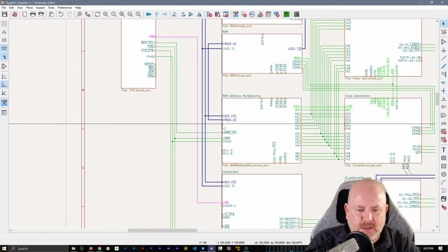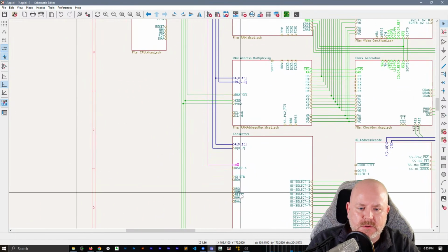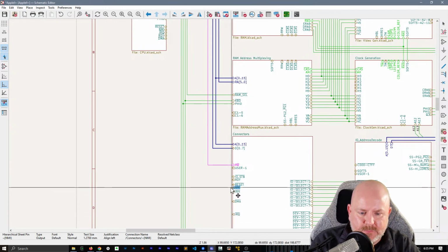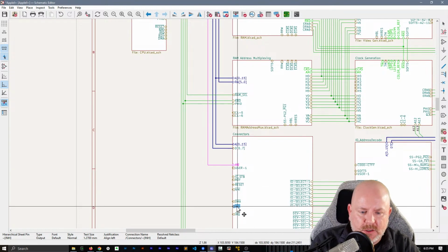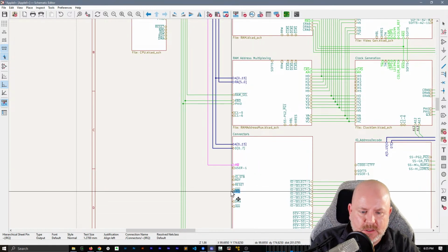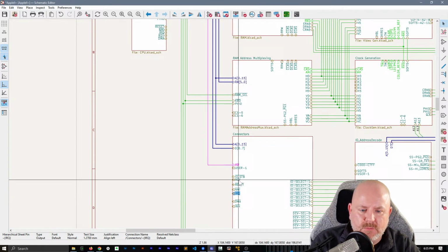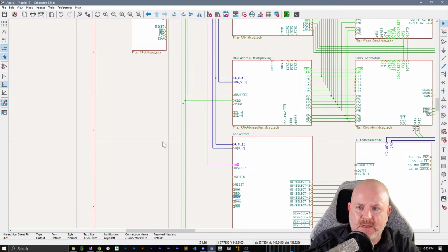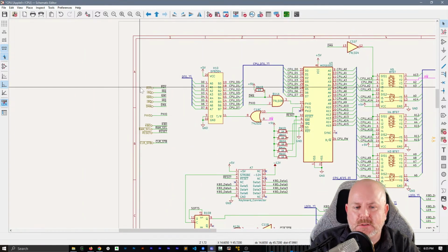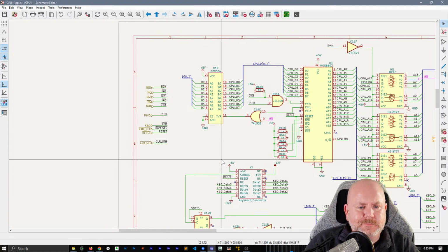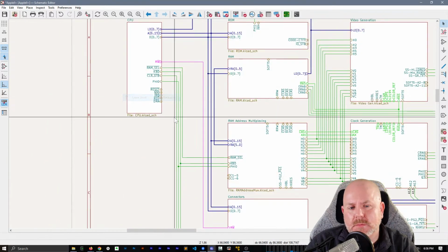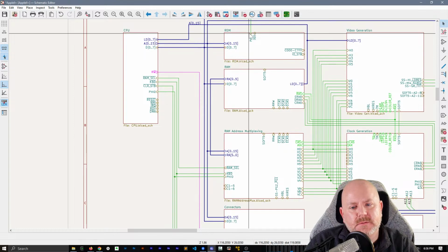So then over on the slots, we'll do the same order. We shall do reset, NMI, IRQ, which is now here, ready, and DMA. What about inhibit? Think. Inhibit is for the ROM. So there it is. Found it.